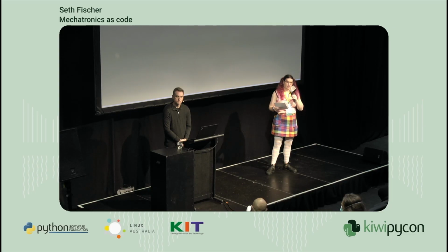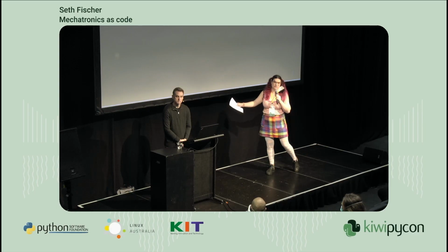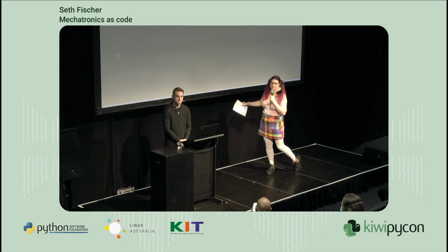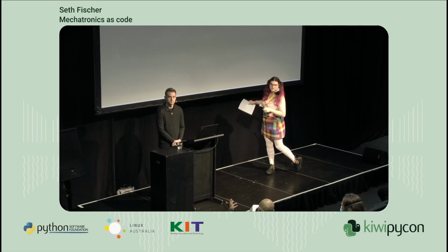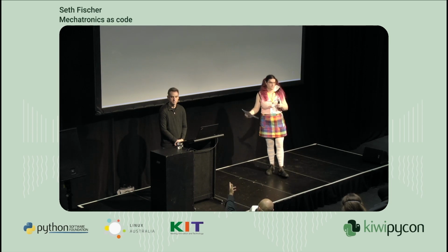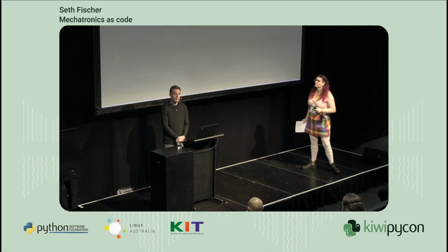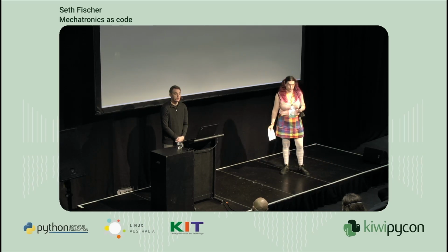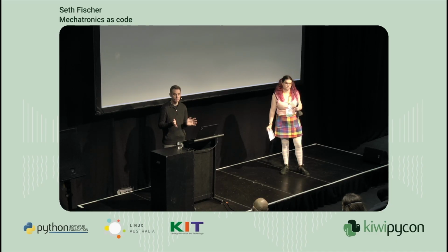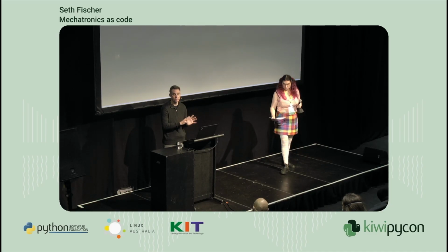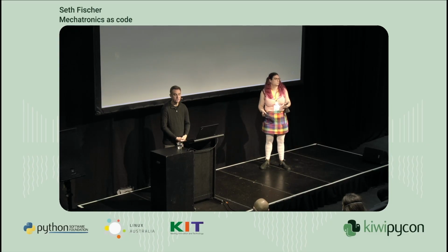How would you in that code define whether it's a through hole or surface mount component? So by default, everything is surface mount. But you can choose a specific part number from a catalog and put that into the Atopile code and specify a specific part, which would be a through hole part. All right.